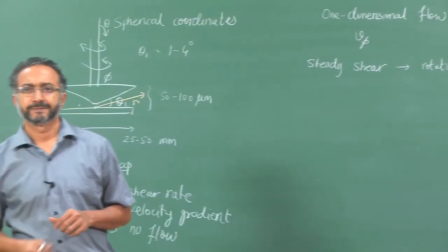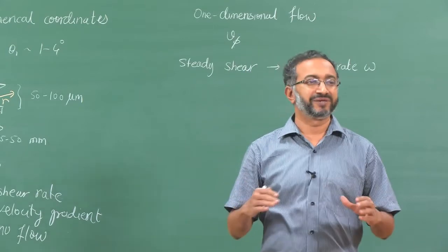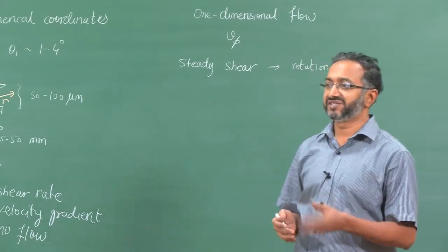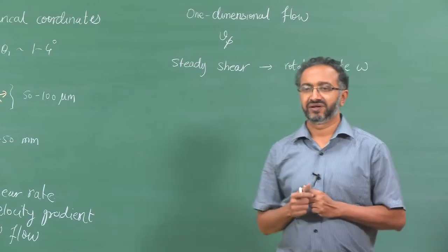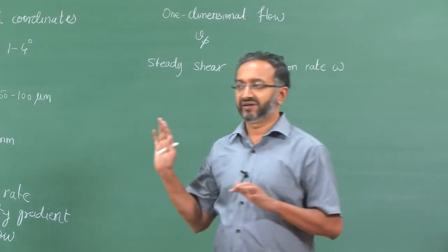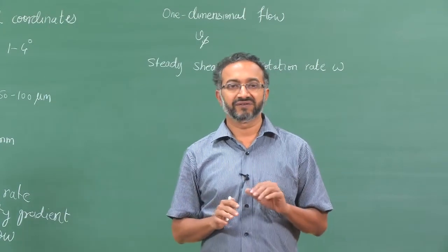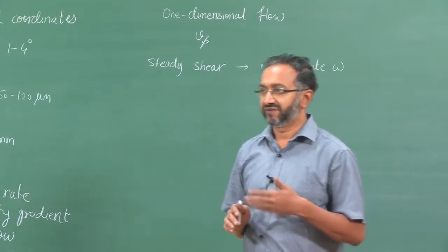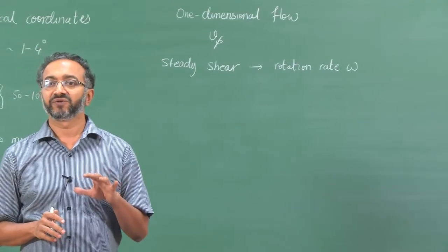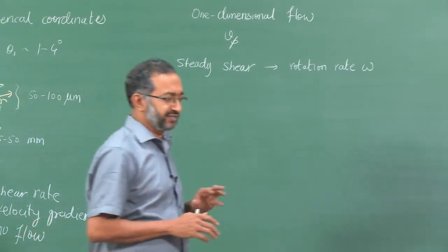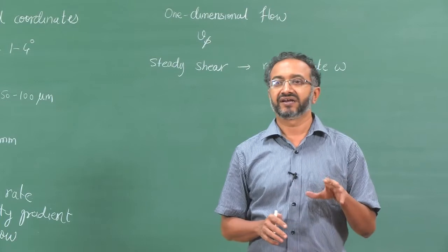So, V_R will be 0 or neglected? Centrifugal action. Yeah. So, the question being asked is, will the radial velocity be 0 or are we neglecting it? In which way should we try to answer this question? In engineering and in analysis of such fluid mechanical problems, there will always be two possibilities. One, there is a fluid mechanical phenomenon, but we say its effect will be minimal and therefore we can ignore it. Or second, we are enforcing conditions such that the radial component will not be there.